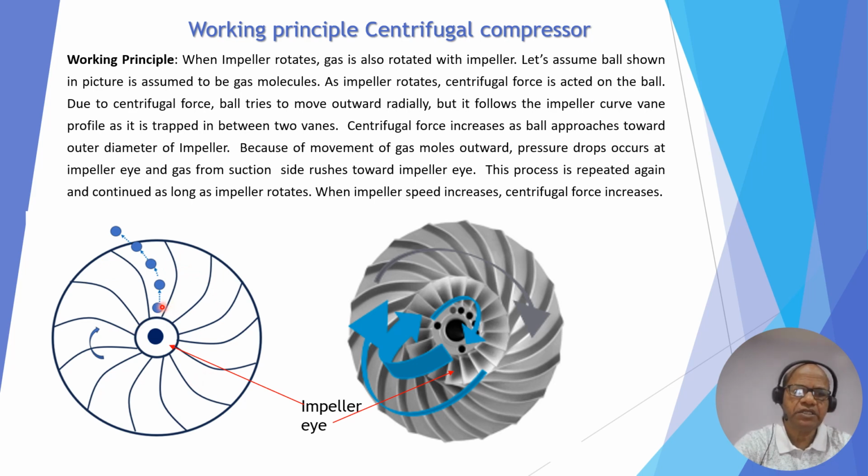Since there is a rotation, there will be centrifugal force acting in the outward direction. But since the gas molecule is trapped in between the two vanes, it follows the shape or profile of the vane. That is why it is moving outward and coming out exactly along the vane profile. Please note that when the molecule is far away from the center, the centrifugal force will be more, and this is how the principle works.